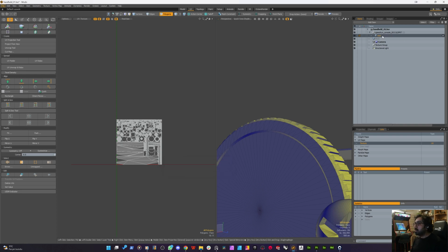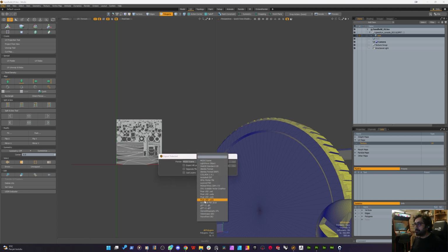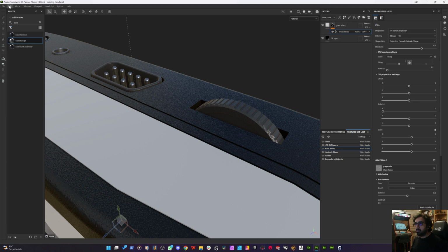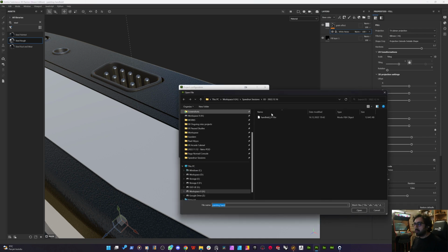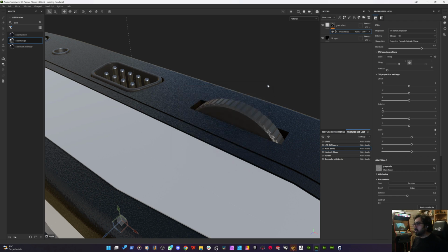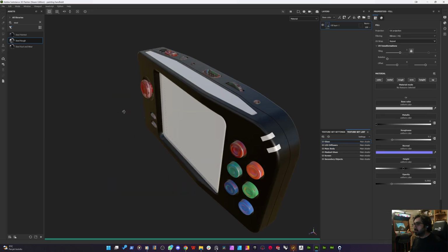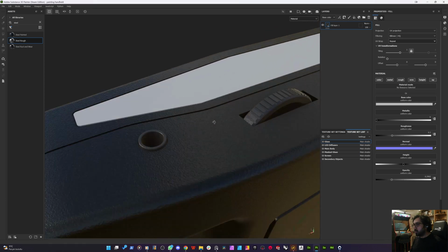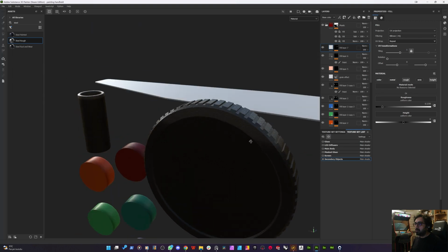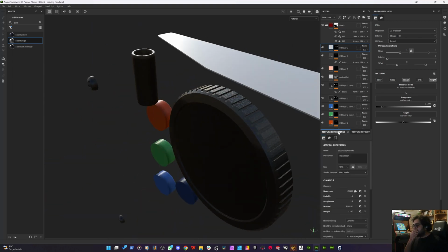Now I'm saving the project file once again and exporting this file to overwrite the existing one. And in the painter, I will first save the project and then, from Edit, Project Configuration, I will reselect the same file. I will keep the preserve stroke positions on the mesh option selected, and now I am re-importing the same mesh. Let me check. All the materials are reassigned, and you will see that the whole volume wheel now stays in the same material group.